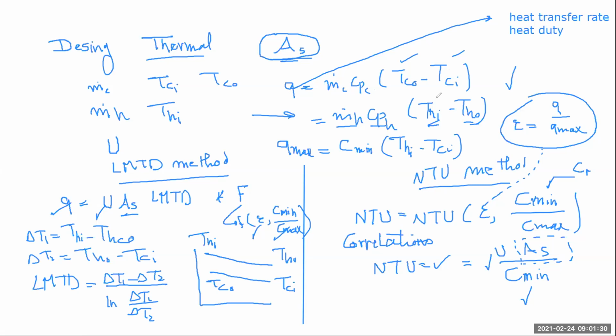So there's no magic number for the flow rate. How much should it be? It depends on what kind of application. And as a matter of fact, based on that, you are going to make the selection of the pump. What should be the flow rate? It depends on your conditions, how hot the fluid that you have is, and how cold is the coolant that you have, so that you can effectively reach a desired condition.